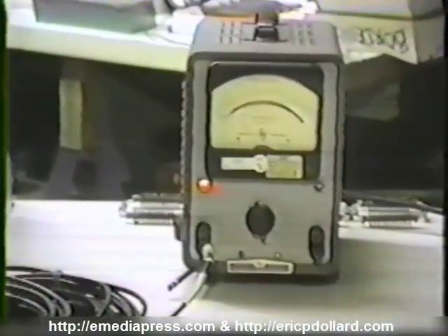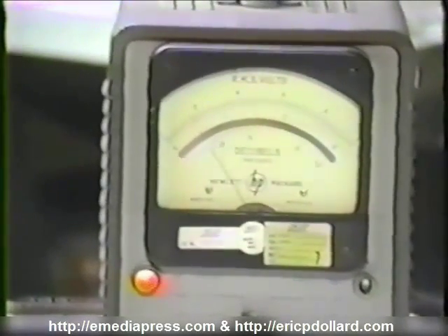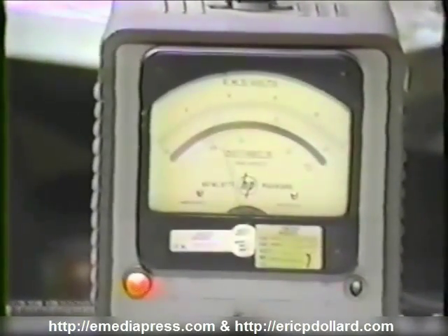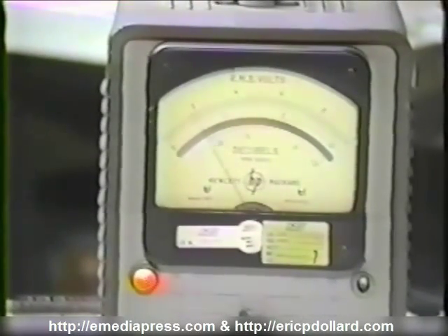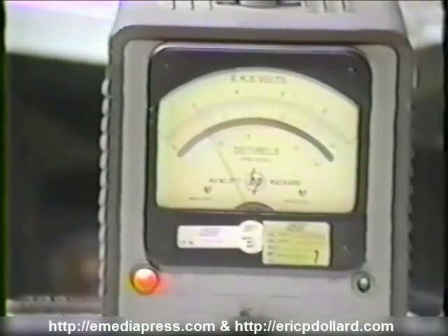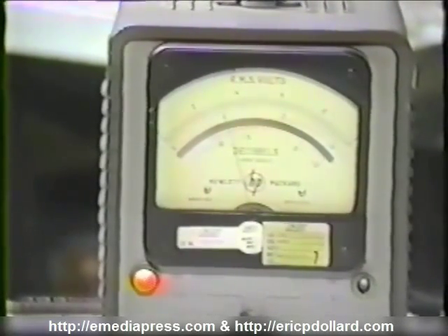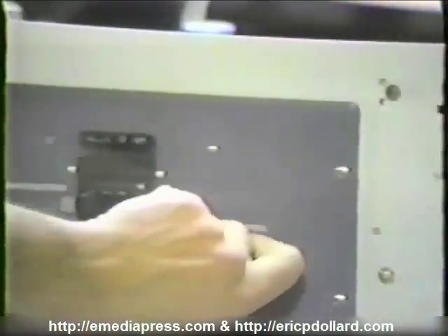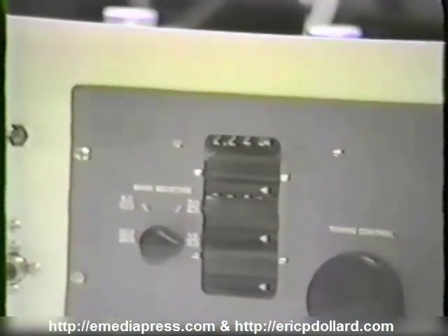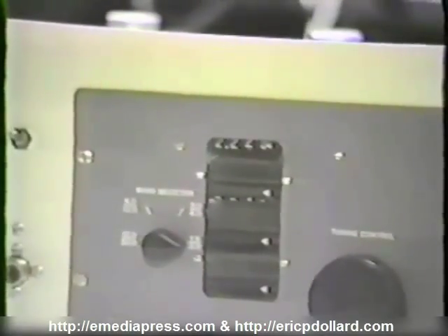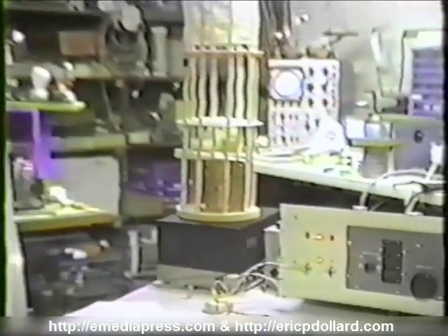Now, as you can see on the voltmeter here, we have a definite peak. So I'm sweeping the oscillator. If we go to roughly our half voltage points, we find we have a bandwidth of about a few hundred kilocycles roughly. And it peaks out at a frequency of almost precisely 2,220 kilocycles. So what we'll do next is plug this into our equations and determine the speed at which our impulses propagate on the coaxial cable.